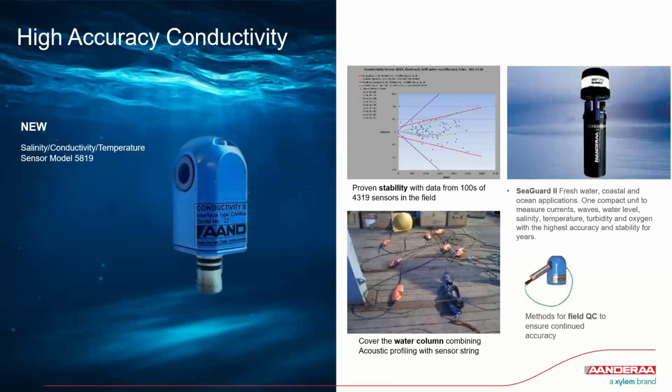And for other sensors, we suggest other methods. For oxygen, you just measure in the atmosphere between deployments, and you can see how much the sensors have drifted, if they have drifted, by comparing with the air pressure. For pressure sensors, the same thing. You can log them in the atmosphere and compare with the atmospheric pressure before and after.